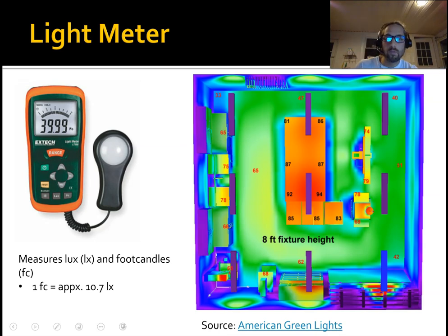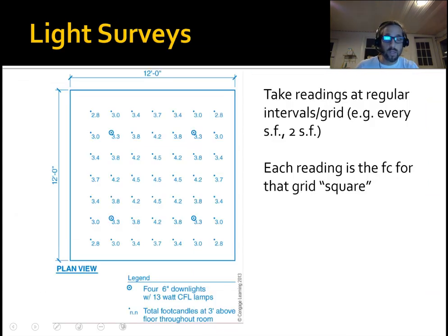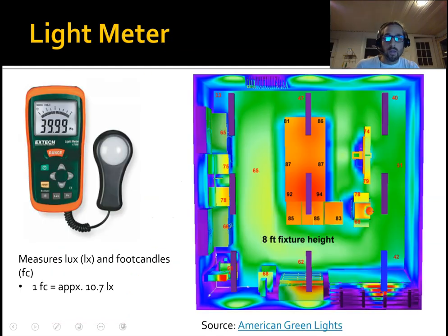So what you do is you methodically walk around a room and measure light levels all over the room to determine whether it is an acceptable light level. You want to hold it at what's called a working level, which in a classroom would be at a computer desk, or desk level. If you're at an operating table, you have operating level. Whatever the case may be, in your workshop it's your desk level. And then you can sketch it out.